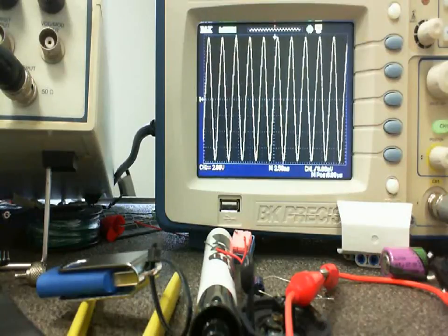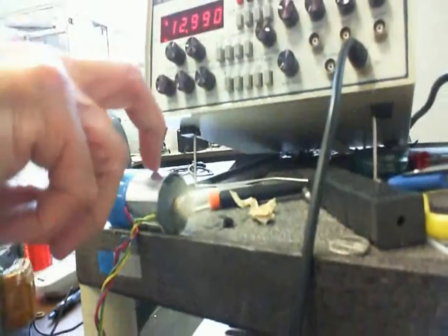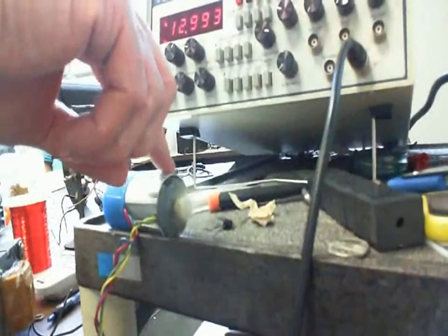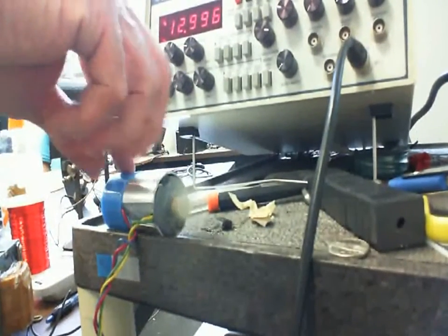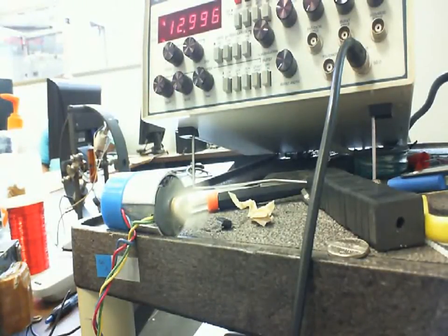Now that's my tape, by the way. Now this thing here is really neat. It's an MG set. I could do the same thing with this guy, but this guy would vary with what? Its output would vary with speed. Now you have to understand this is two units in one. This is an MG. It's got a tach generator in it and a motor, and this was in a speed control system. And it controlled the speed of the floppy disk, how fast it spun the disk around.